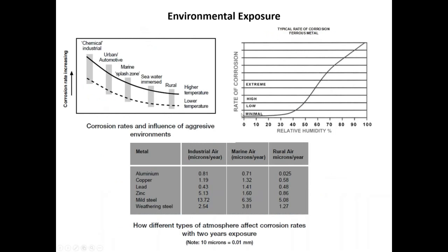Another is the environment. So when we talk about the environment, we are looking at the presence of moisture. We're looking at temperature, as you can see here, because of the Arrhenius relationship. With the equilibrium, the higher the temperature in general, the higher the corrosion rate, and the more chemically degrading or oxidizing the environment is, the higher the rate of corrosion. Another is you can look at humidity. So very clearly in tropical environments or areas where you have high humidity, you have higher rates of corrosion, or simply just the quality of air.